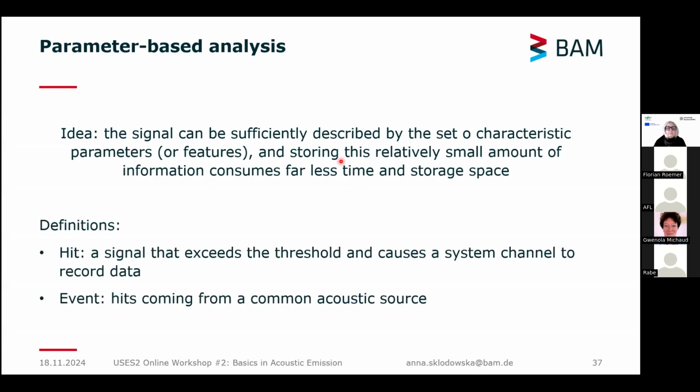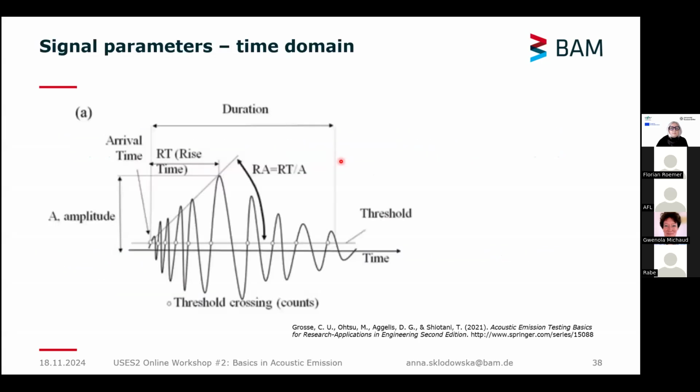I will use here two different terms, which I want to say in the beginning. First is a hit. When I refer to a hit, I mean a signal that exceeds the threshold and causes a system channel to record the data. An event is a bunch of hits coming from a common acoustic emission source. So these are just two different definitions.